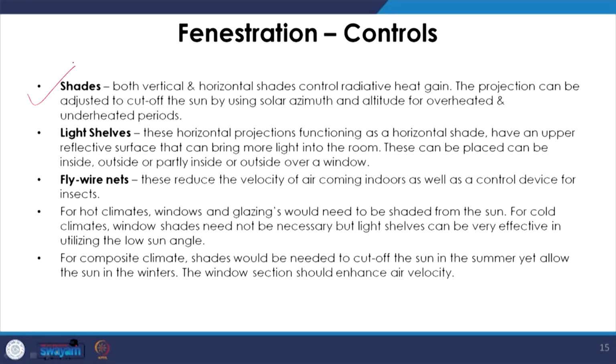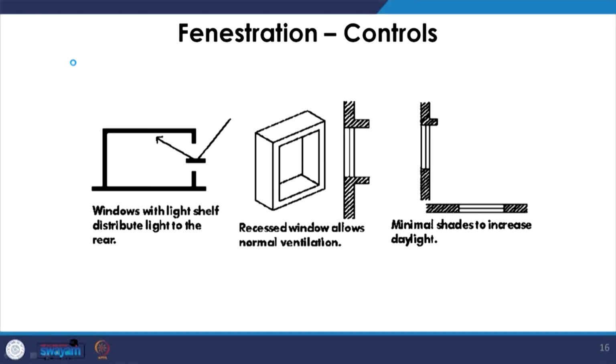A light shelf is a very interesting concept where, above the window, so this is the window, and above it we have a shelf which is a permanent feature, and the upper surface of this light shelf is quite reflective, very light in color.